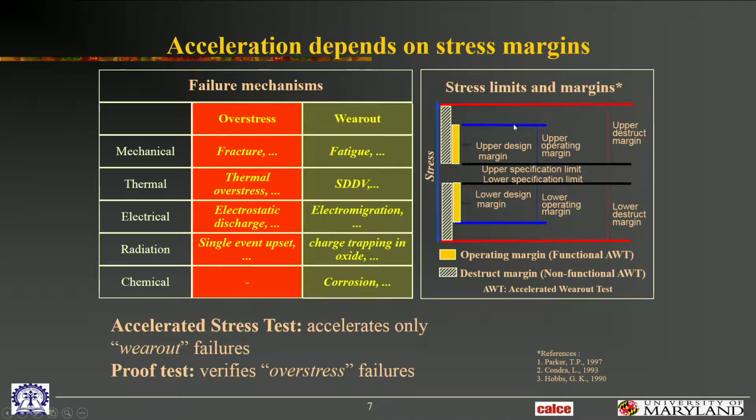We talk about two kinds of overstress limits. One is what we call an operating overstress limit. That means if you go above that, the product may not electrically function correctly, but it's not dead. If I reduce the stress values, it works fine again. But above that stress level, it drifts off its functional parameters and is not going to function satisfactorily. That is what we call a reversible or soft overstress limit, because the product is fine again once you bring the stresses back.